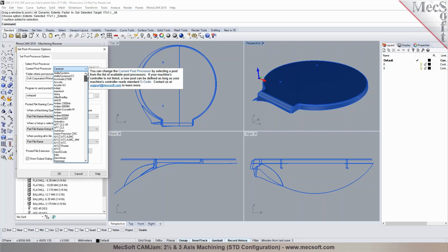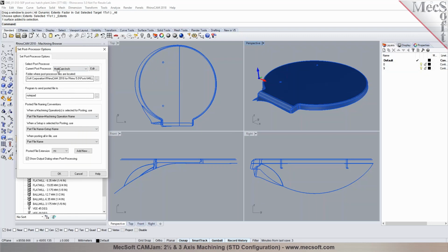So the post processor is listed by the name of the machine tool or by the controller name. Do you happen to know what tool you're working with? Yeah, I work with a Multicam 5000. Okay, and the actual name of it is not on there, but I'm guessing if I contacted Multicam, they would tell me which processor would be the correct one. I would recommend using the Multicam Inch. This will work with pretty much most of the Multicam machines. Cool, that's the one I was actually guessing would work.